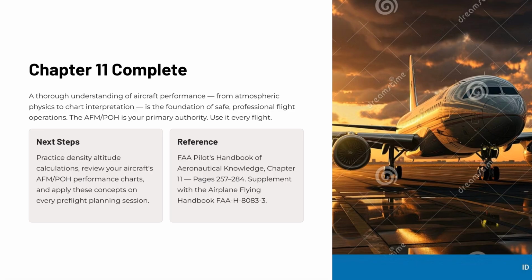On that day, at that airport, in those conditions, your primary authority is always the Airplane Flight Manual or Pilot's Operating Handbook for your specific aircraft. No general rule of thumb replaces the data found in those pages. Make it a habit to consult your performance charts on every pre-flight planning session, not just when conditions seem challenging.